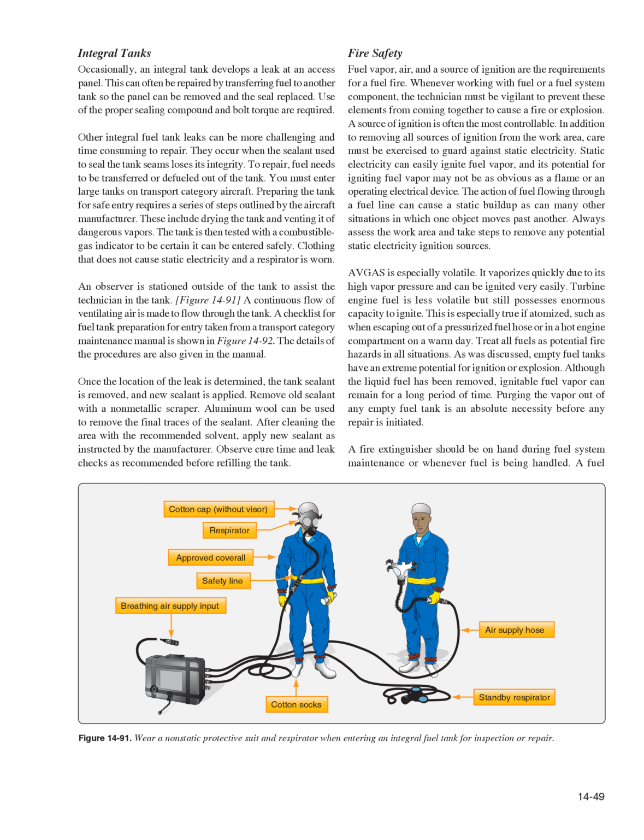Remove old sealant with a non-metallic scraper. Aluminum wool can be used to remove the final traces of the sealant. After cleaning the area with the recommended solvent, apply new sealant as instructed by the manufacturer. Observe cure time and leak checks as recommended before refilling the tank.